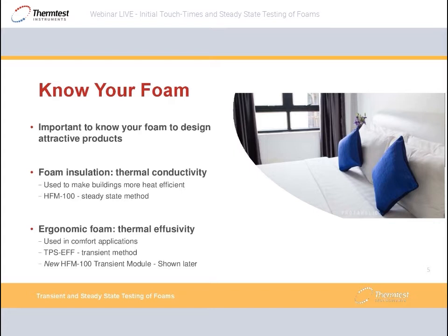Now, it's important to know your foam. You need to know the properties of your foam if you wish to design foam that is attractive to a customer. When it comes to things like foam insulation, we look at thermal conductivity, because in an application with foam insulation, you're trying to insulate a building and make the building more heat efficient. So you could use a HFM 100, which is a steady state method, which will measure thermal conductivity.